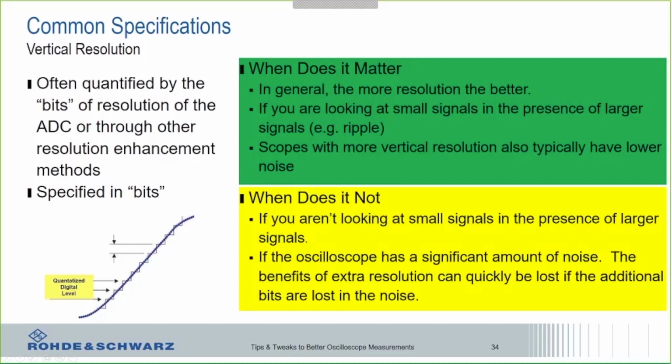So when does it not matter? Again, if you aren't looking at small signals in the presence of larger ones, or if you're buying a scope that has a lot of resolution but has a lot of noise, you're really not going to get any benefit out of it.